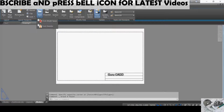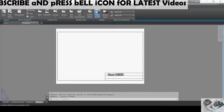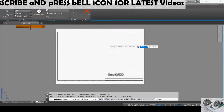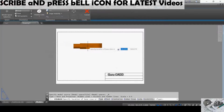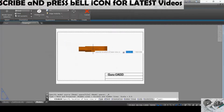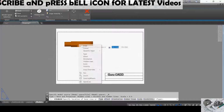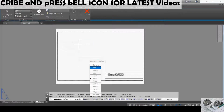Now select the base button, select from the model view and click inside the page. If you observe, your view is created. You can change the orientation of the view by right clicking and selecting orientation.